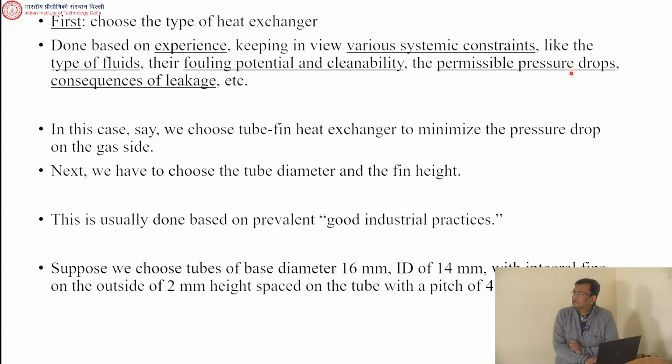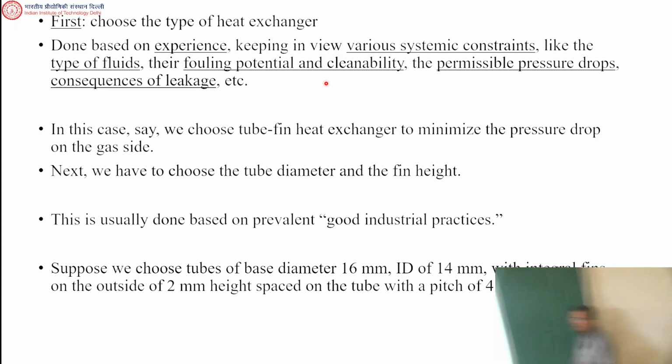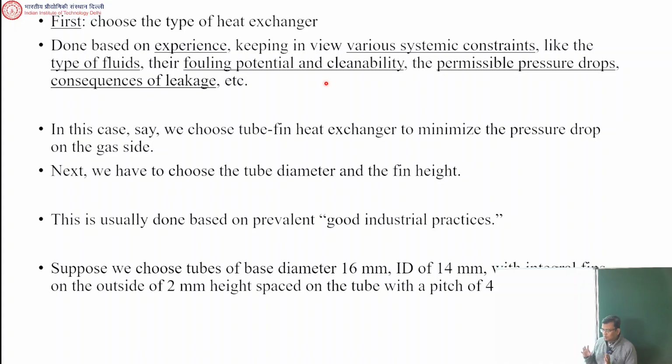For example, it also depends on the type of fluids that you have, and their fouling potential and cleanability. So which fluid do we think about before we choose the type of heat exchanger? We think about what kind of fluid will be used and how much fouling it can do.